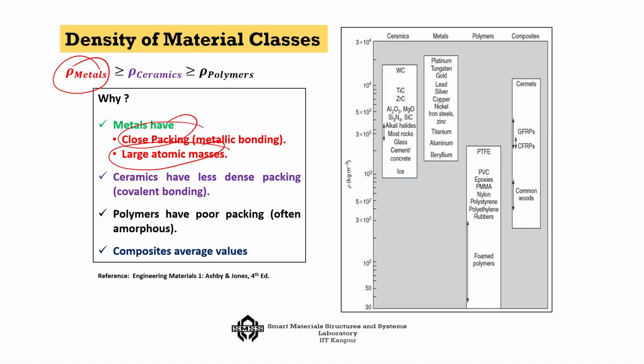In terms of density, no wonder that except possibly aluminum, beryllium you can rule out because it is very corrosive in nature. So, aluminum, and the next good is titanium. Okay. And in terms of the density of ceramics, it is the glass, cements, etc. And in terms of the density of polymers, the highest will be of similar order, that is polytetrafluoroethylene, PTFE, and most of them are much lower, as you can see here.